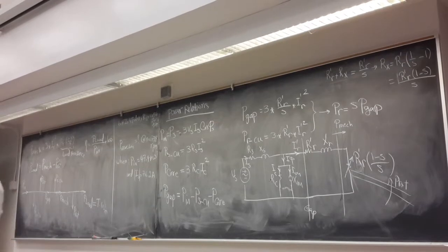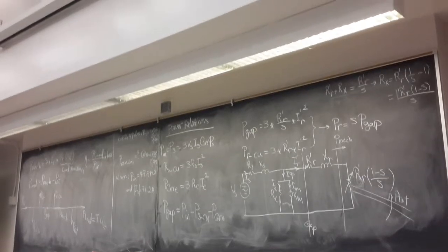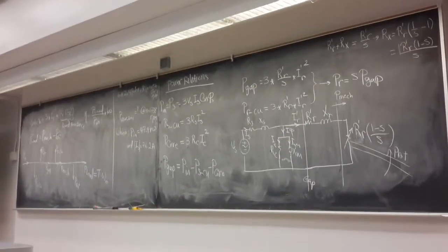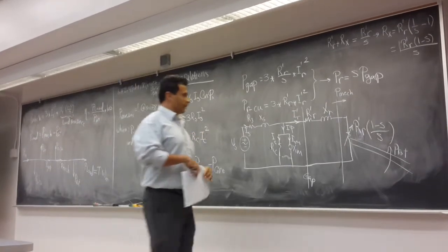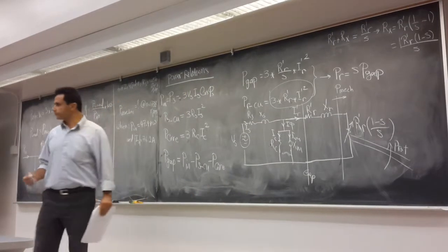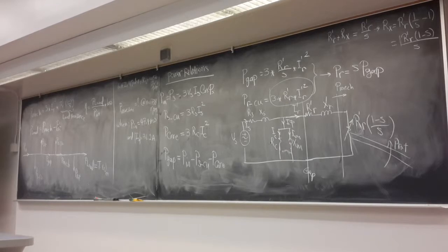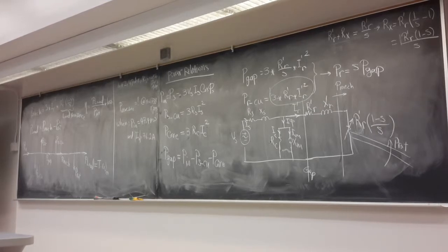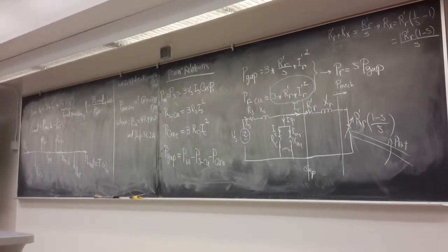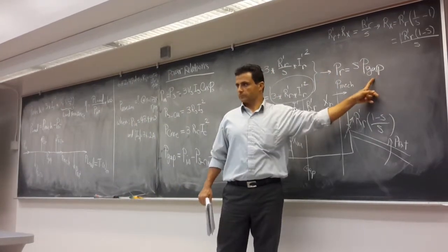Let's understand what we are looking for. What is the rotor loss? This is the copper loss in the rotor, right? We don't have any other loss in the rotor, it's the copper loss. So, if I want to calculate the copper loss, should I use this equation? Why? It's the only loss in the rotor. No, you cannot. Why? We don't know how much is our R prime. How about this one? Can I use this one?